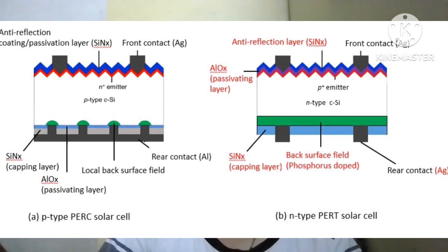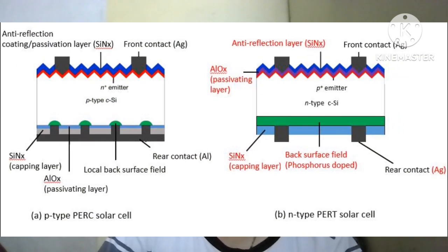A solar cell has two different layers of silicon. One is called the P-type and the other is called the N-type. The N-type semiconductor can give away electrons easily. The N-type semiconductor faces towards the light. The P-type semiconductor can receive extra electrons. We call the spaces for these extra electrons holes. This semiconductor is underneath the N-type one.